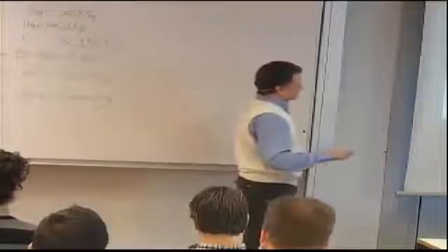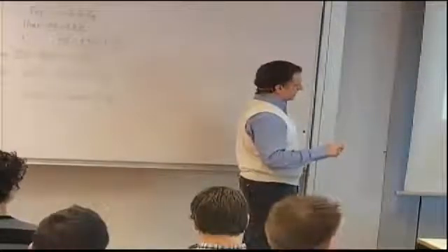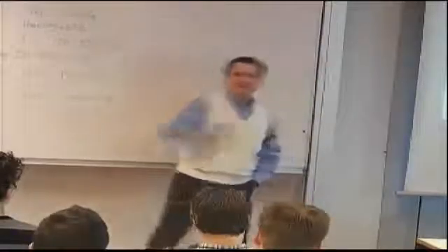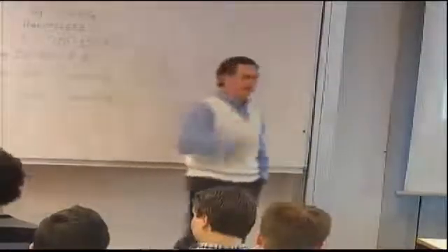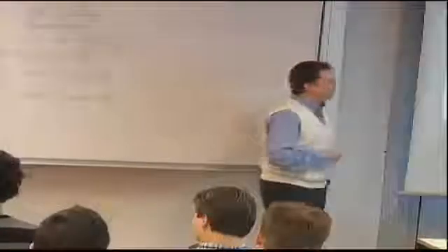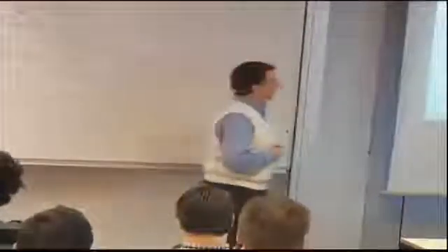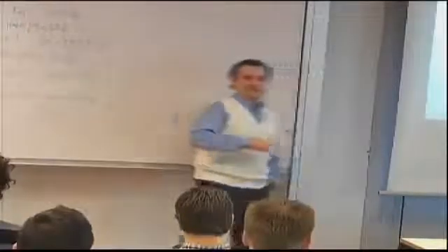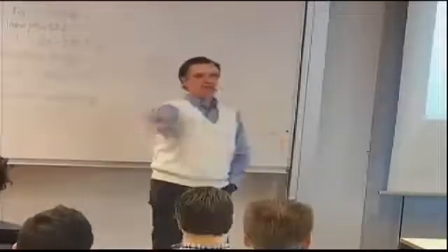But you take this distribution of the, I'm sorry, these are the highest loads. You take this distribution of the highest loads and the 95th percentile, or something along those lines, could be 90th, could be 99th, depending on the application, becomes your applied load, accounting for variability in how that maneuver, a 3G turn, might be flown, for example.